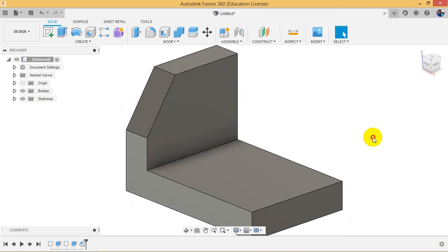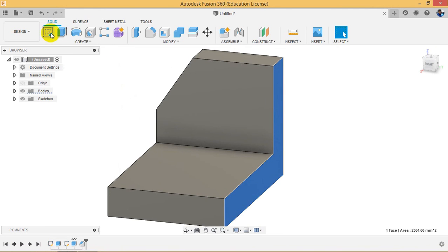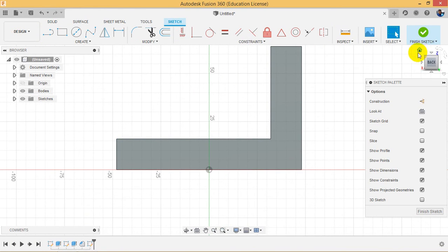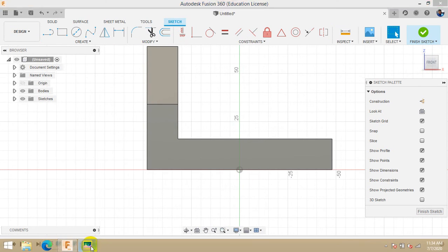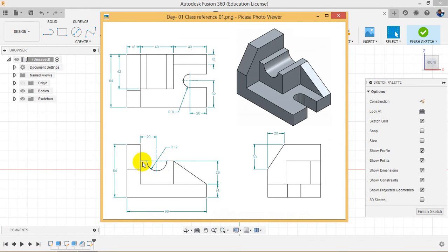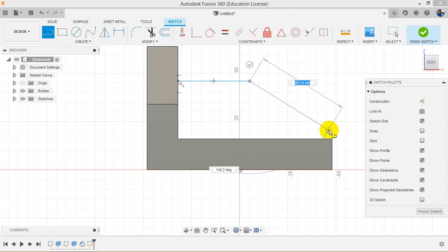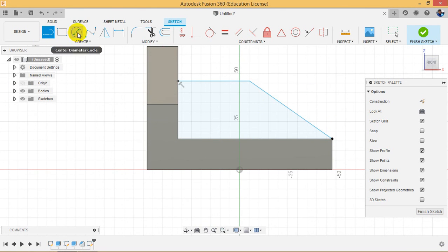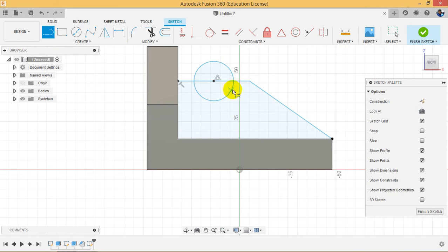So I'm going to create this. Let's just create the shape first. So I'm taking this plane, we are working on this plane, so that's a wrong direction of looking at. I'm going to look at exactly how the sketch is showing me, so that is how you can draw it. So I'm taking the line command in here and creating the line like this, and then I'm creating a circle in here at the center point, at the midpoint of this, and then I am creating a line to close this.